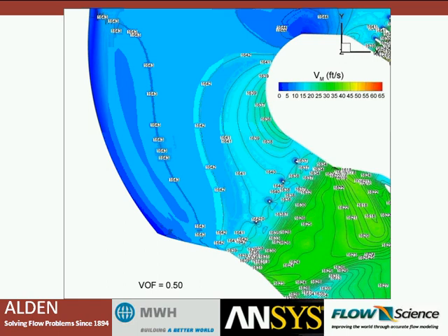And then a picture here to give you an idea of what we looked at in the CFD model. And this doesn't capture the entire domain. The entire domain of the CFD model is what you saw in the slide 2 slides ago. But this slide is colored by velocity, and it has contours of water surface elevation at the same time. And we can look at what the predicted water surface elevation is for a given flow.